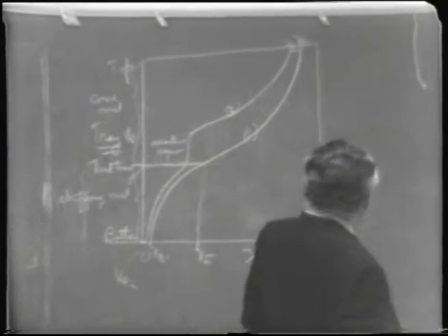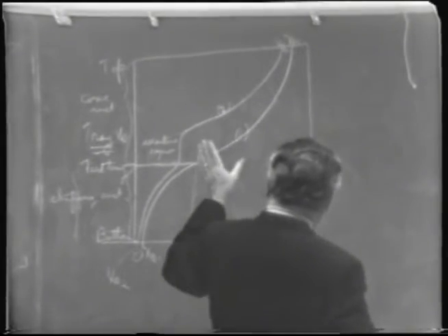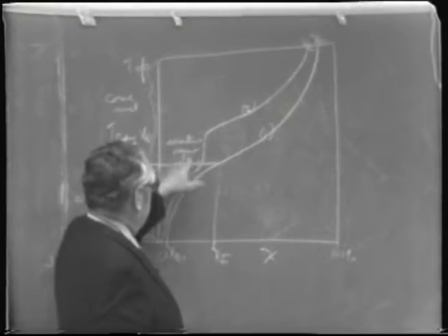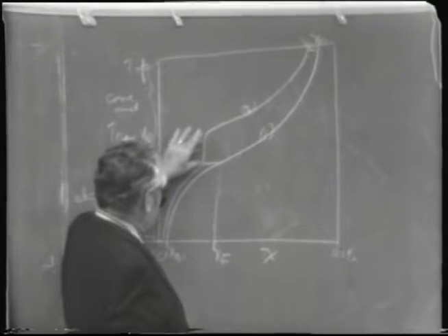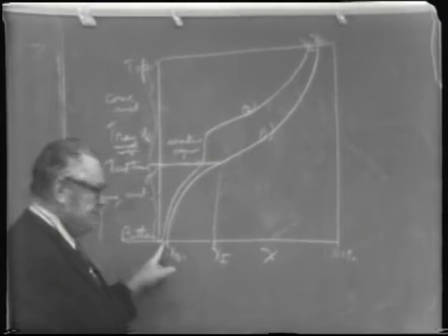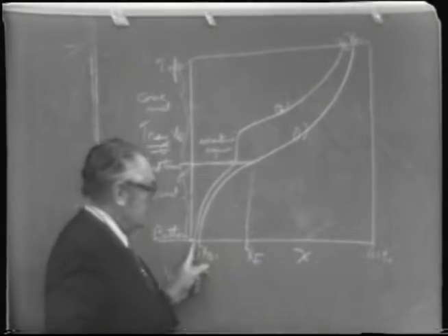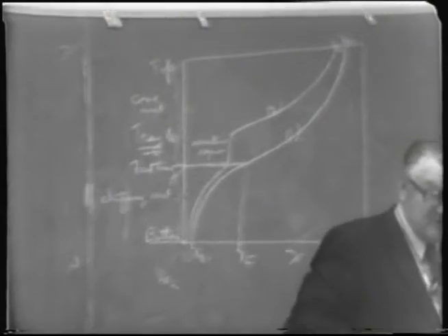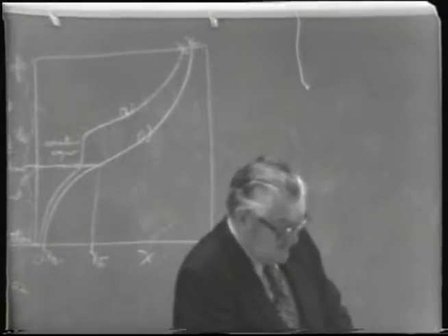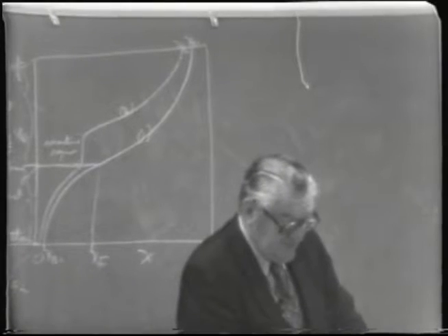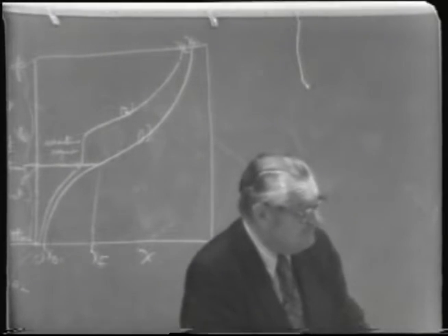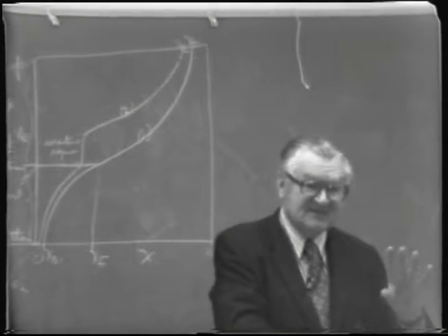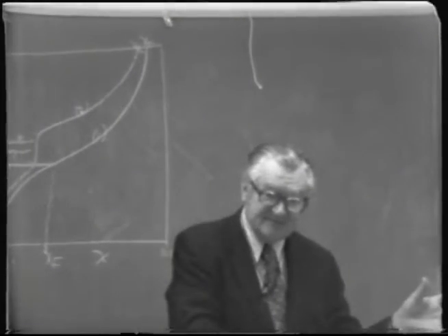So in other words, you could say it another way: when you operate a column this way, you get an inactive region above the feed tray, but it will result in somewhat better stripping of the volatile component, but a lower product quality, at least a lower product concentration, than would be possible under the ideal situation. The ideal situation would be that for which presumably the existing column was originally designed.